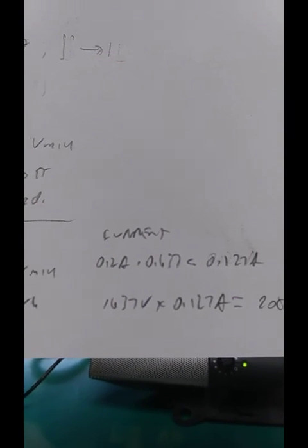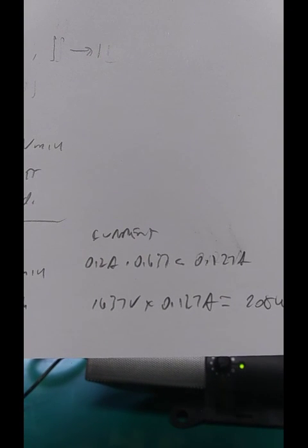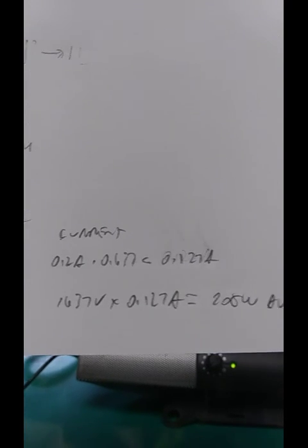For the current, we take 0.2 of an amp from the plate curves for the 1 kV swing, times 0.637, equals 127 milliamps. 1637 volts times 127 milliamps equals 208 watts average, and that is an exact figure. In engineering, that is a defensible figure because I can go back and point to the process wherewith I calculated it, but you can rest assured it's not accurate, because I did not include that extra 10 volt swing.